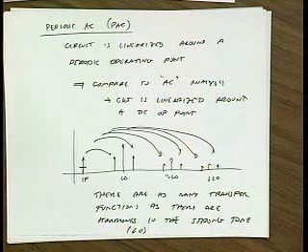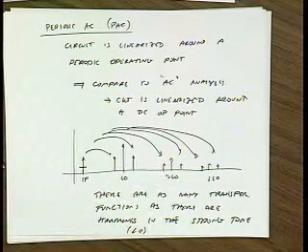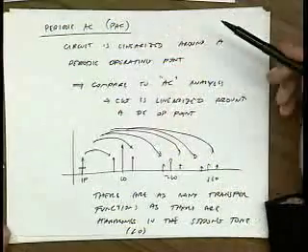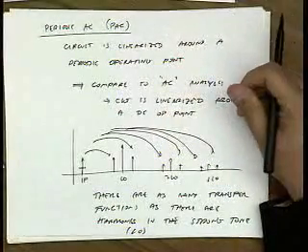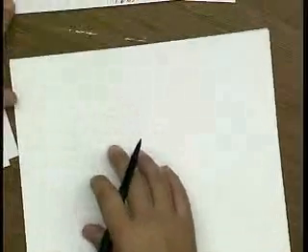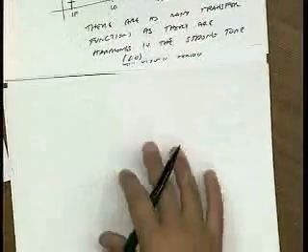Okay. Kevin, it looks like you have a question forming in your mind. What does it mean for a transfer function when it's not linear? It means output over input, right? And that's the problem. It is linear, but it's time varying. This is a linear analysis. That's why it's called AC. So what we need to do is specify a reference. Basically, we have to specify which transfer function we care about.